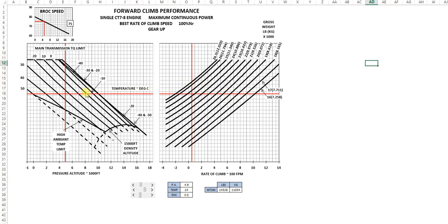The 50 feet rate of climb at LSALT, we used to work out for our Cat A calculations. Okay, pressure altitude, temperature, rate of climb, we used to leave it at 0.5. Pressure altitude, that's the pressure altitude at your LSALT, the temperature at your LSALT, and your maximum takeoff mass to be able to maintain that rate of climb at that pressure altitude and that temperature.